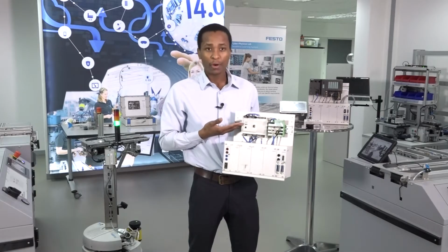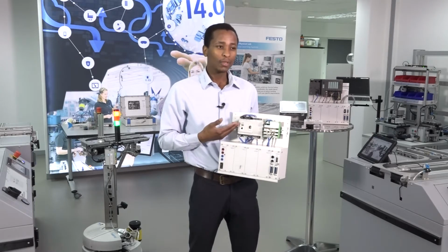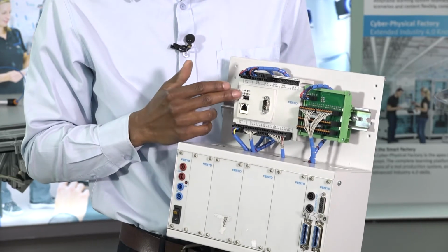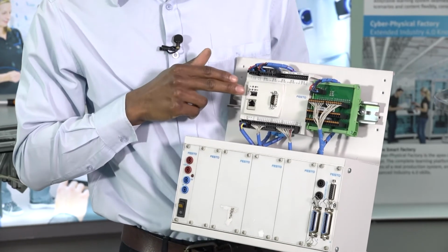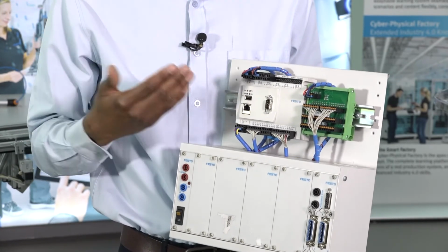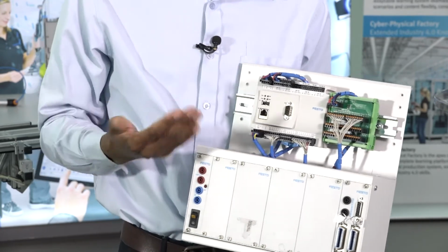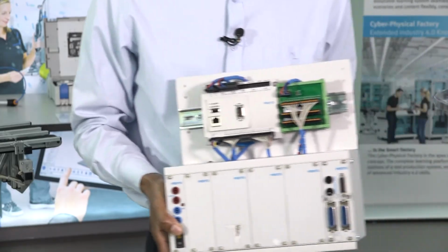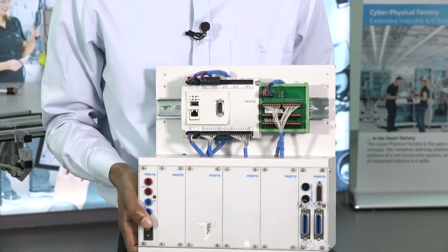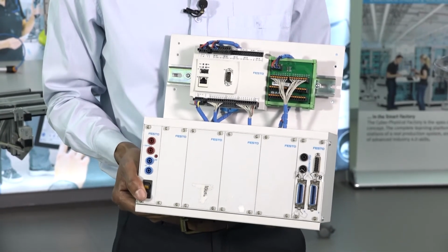It has an Ethernet port for communication. This is where I load the program. Also, for what we call Profinet communication, this can be done here. And then this is the USB, where you might want to load a program into USB if you don't want to use Ethernet. This is CAN bus. When you talk about CAN bus, this is another field bus protocol where you could be using the PLC to control an electric drive or any other industrial device that is capable of CANopen.